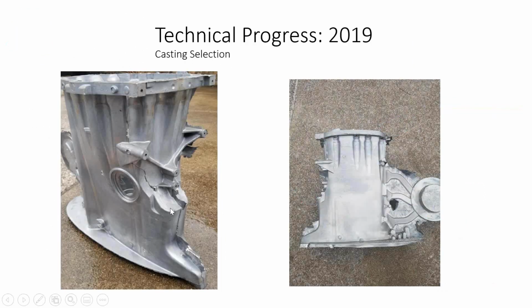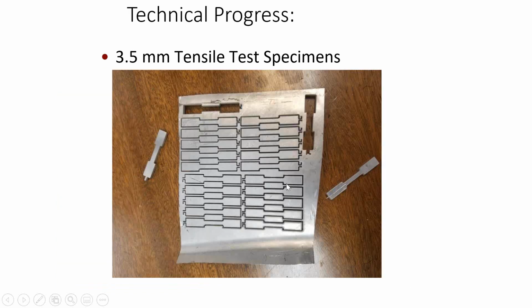So this is a die casting that I completed. This is a rear end motor mount housing for a marine application, and this is B360 alloy. From the sidewalls of those castings, we excised samples. Now, I couldn't get down to a 3 millimeter sample, but I got to a 3.5 millimeter sample. I physically had these water jet from each one of the castings, and you can see the tensile bars. Once they're water jet, you can just break them out. And then they're only machined on two sides with skin left on two sides.